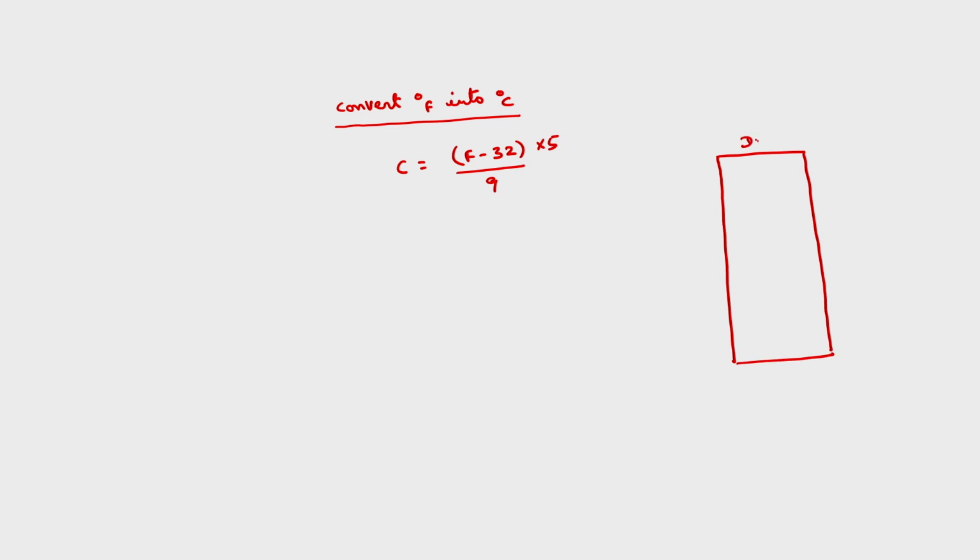So in the data segment, let the starting of this one be 50,000 H, and with the offset of 5,000 H the value of Fahrenheit is stored. And we store the result centigrade in the location with an offset of 6,000 H.